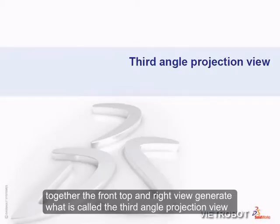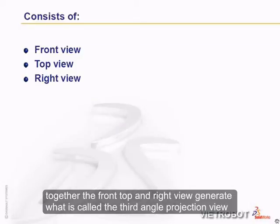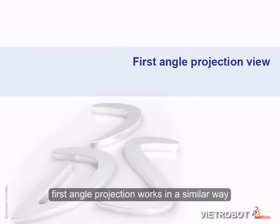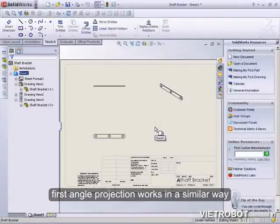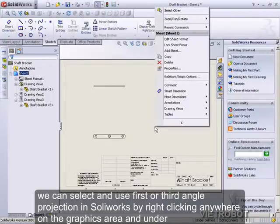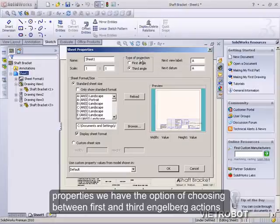Together, the front, top, and right view generate what is called the third angle projection view. We can use the three views to generate a three-dimensional object in 2 dimensions. First angle projection works in a similar way. We can select when we want to use first or third angle projection in SolidWorks by right-clicking anywhere on the graphics area. Then under Properties, we have the option of choosing between first and third angle projections.